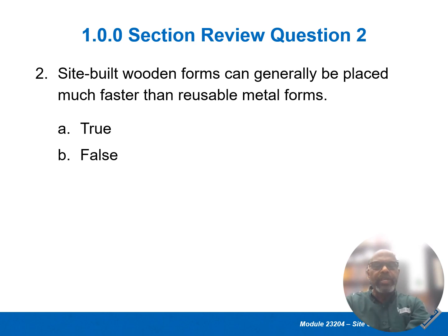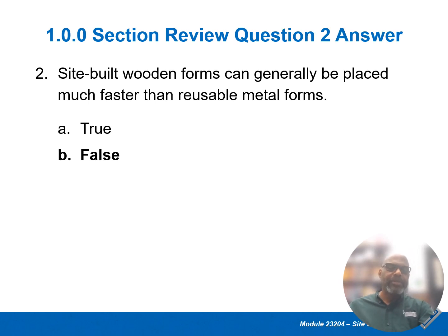Site-built wooden forms can generally be placed much faster than reusable metal forms. That is certainly false. Those reusable forms are designed for that purpose, to speed up the process and get things done without a lot of assembly compared to a wooden form.